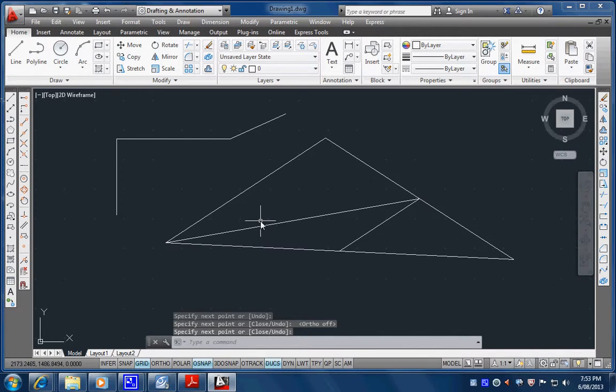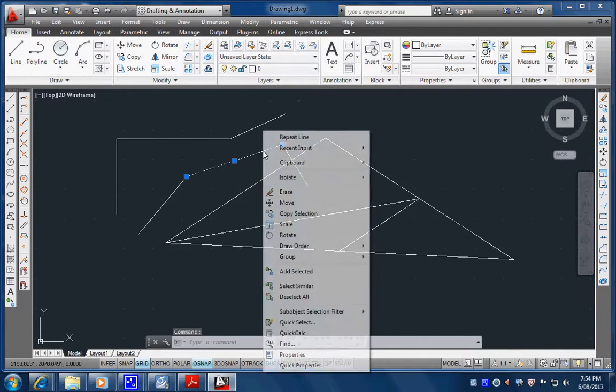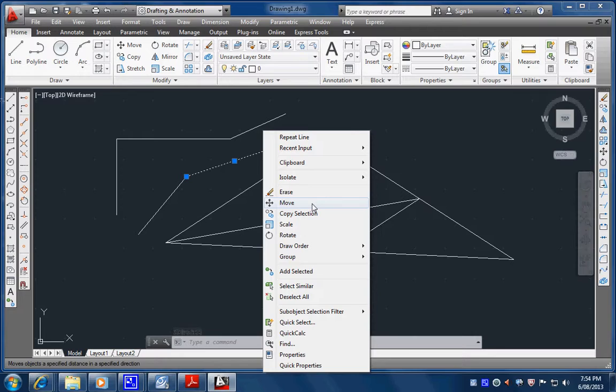One thing you need to know that's very important is your mouse. When I'm clicking here and picking the line command, I'm using the left mouse button. It'll tell you in the book if you need to right click, for example. There are a number of ways of inputting commands, and one way obviously is this and this. The other way is typing. There are the menus up here, draw. It's another way, a bit obsolete and old. Another way some people do for modification commands is click on something first, right click and issue a command. The book approaches it more by issuing the command first, then selecting something, but you can also do it the other way around. Just the prompts might be back to front a little bit from what you're used to if you did it the other way. So just be aware of that.